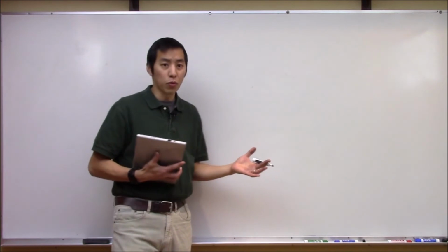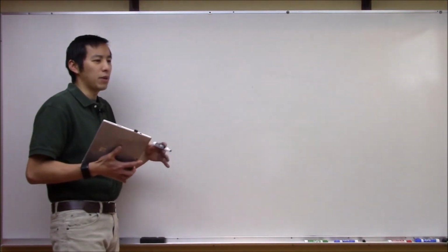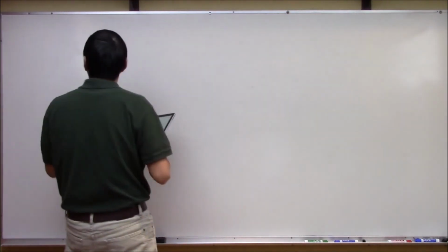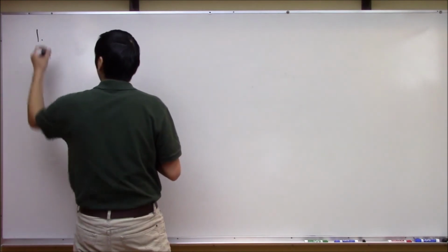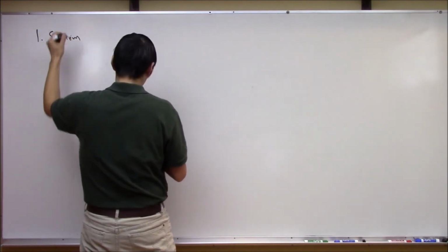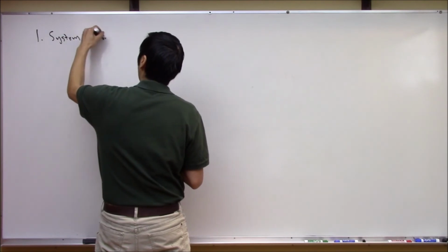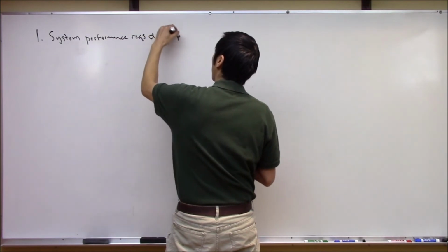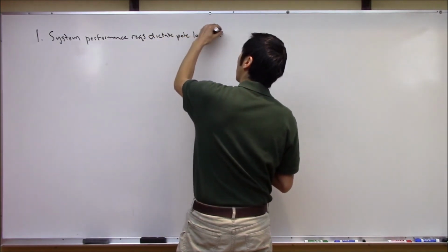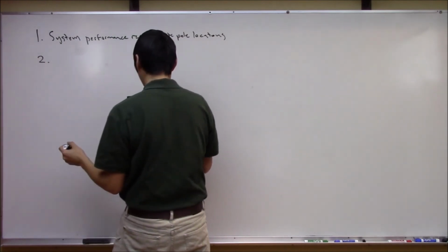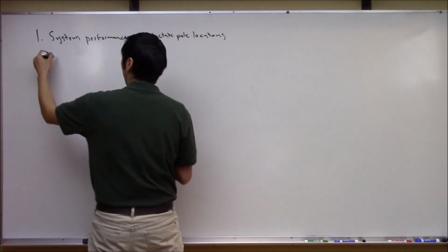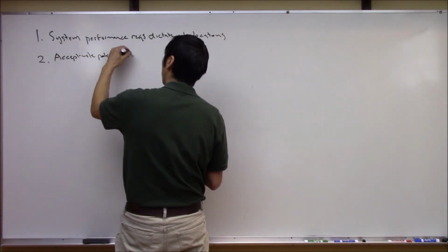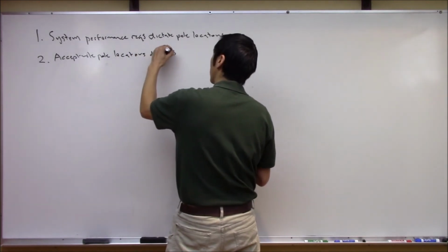At this point, I think we have a really good workflow for discussing the general theory and concept of how we can design a controller to meet specific performance requirements. So we saw that what usually happens is that these system performance requirements will dictate pole locations, right? And based on these pole locations, that's going to drive our system design. So we can say that acceptable pole locations drive controller design.